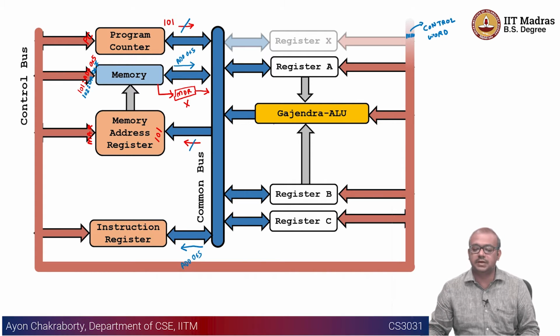Sometimes it is not always that we are going to increment the program counter by 1. Sometimes I want to have a function call, or I want to go to a different place in your program, which is somewhat relatable to a jump instruction, or the go to statements you have used, where depending on the condition you jump to a different place, you transfer the control of the program to a different place in the program.